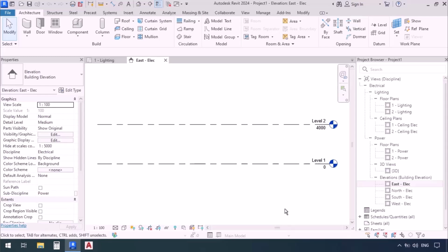For now, in this video, we're just going to try to draw some cable trays for practice, and generally become familiar with how we can do it. After we learn how to draw them, the whole process is going to become completely project-oriented, and then we're going to work on a project for which we have the architectural and structural plans, and then we're going to draw the actual cable trays for that project. So remember, when I open the one Power floor plan, I'm going to be drawing the cable trays for level 1, considering that this would be the ceiling for level 1 or the floor of level 2. So we're going to be drawing the cable trays around here near the ceiling.